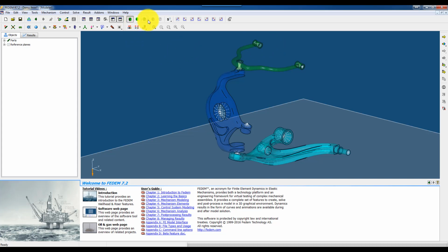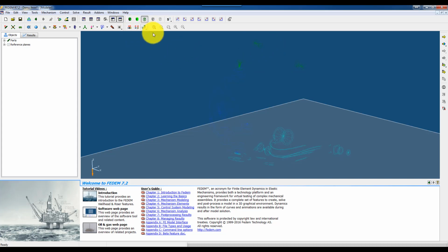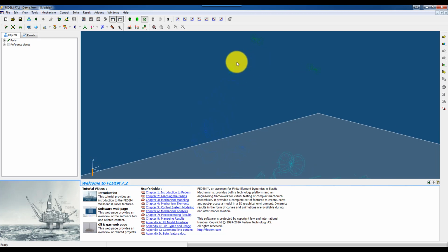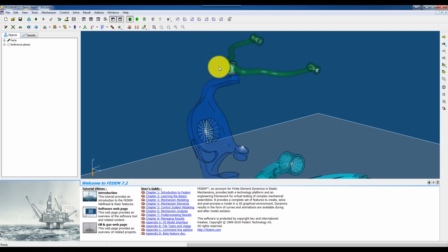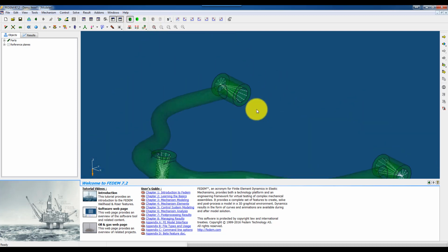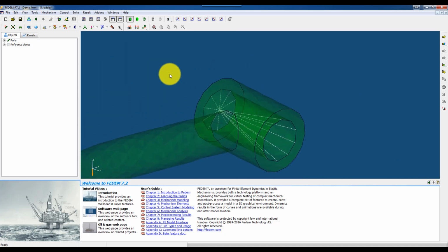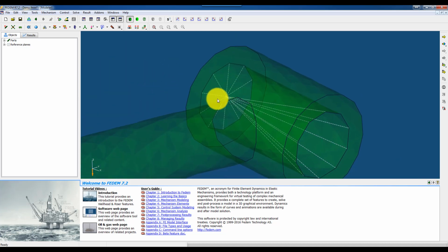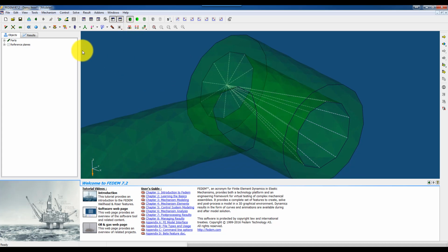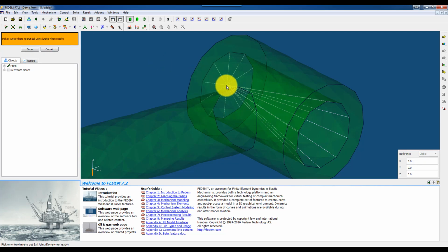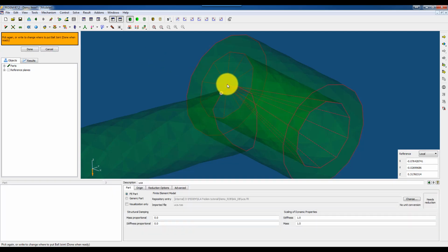When I do this, I choose to not have a solid view, but a line view. Okay, I use transparency, so that wasn't perhaps a good idea, but I can zoom. I use F1 to pan and F2 to zoom. And then I go on this menu and I choose ball joint. And here I click on the center, and it was a bit difficult because it's a solid view, so I click on a center of an RB2 element where I want to put the ball joint.